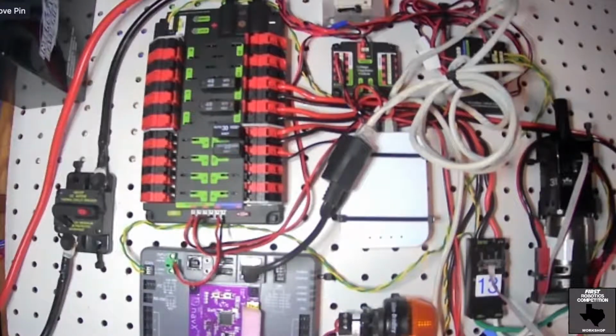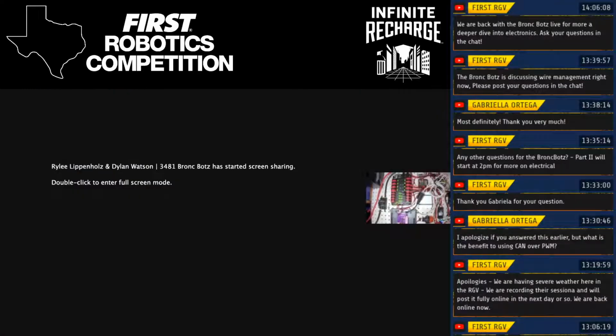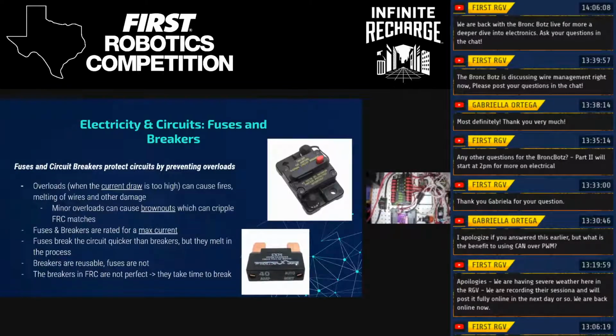Oh, the other thing about breakers that I want to go over just really quick is that these breakers, while they are self-resetting, are not instant. So you can still draw too much current through your motors, especially if you're stalling them, so running them to the point where they can't spin anymore. They will pull crazy amounts of current, like up to 200 amps, even though it's a 40 amp breaker, because the breaker takes just a split second to shut down the power. So there's still the ability to pull too much. You have to really be careful not to stall motors. That is the #1 reason that I see why robots die on the field, is because of a stalled motor or bad wiring, one or the other.